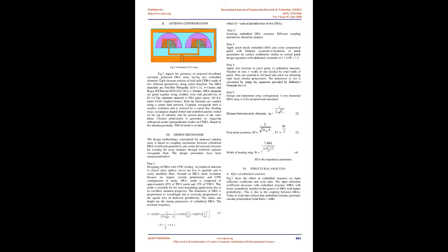The array structure combines the signals from individual resonators in order to achieve improved performance compared with a single antenna. This reduces interference and is more sensitive in a particular direction, thus maximizing the signal to interference plus noise ratio, SINR. Near/far field antenna measurements such as reflection coefficient, axial ratio, radiation pattern, radiation efficiency, and gain were simulated and analyzed using ANSOFT HFSS software.